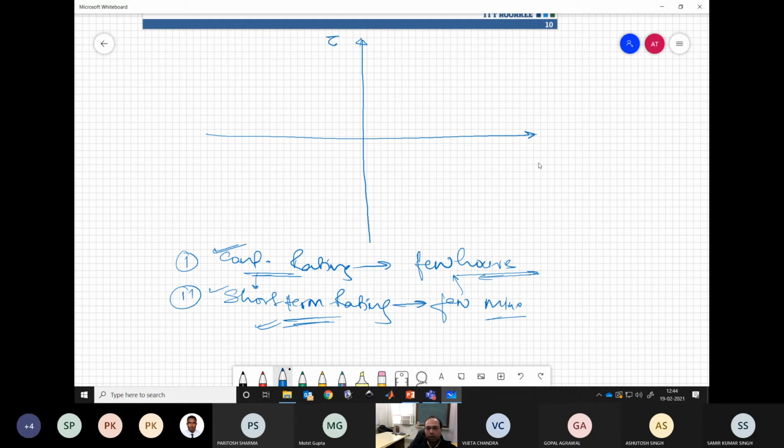Now on the torque-omega axis, the limits on omega are dictated by the mechanical bearings. So we do have a rigid limit there, which is the same whether you call it short-term or continuous. Here we do not have any short-term limit.